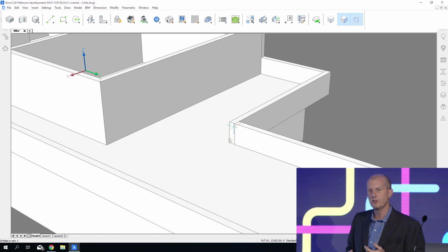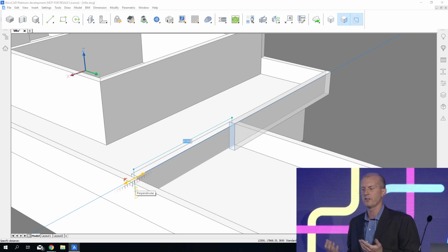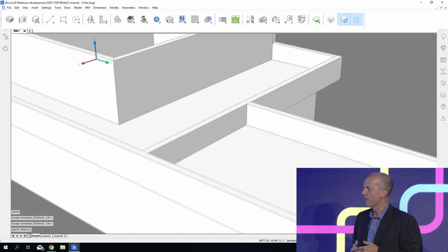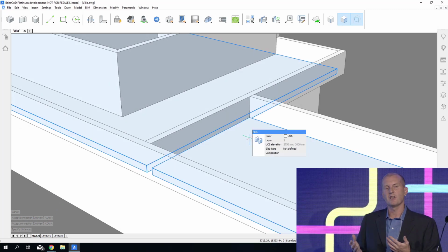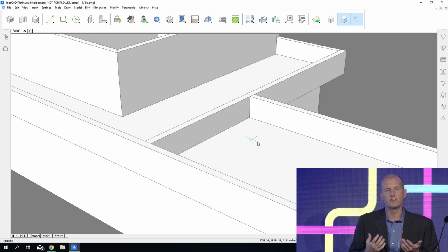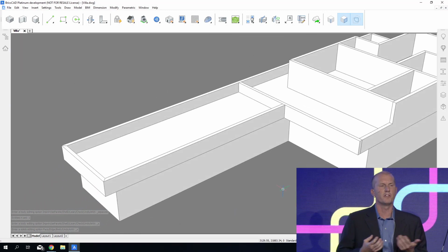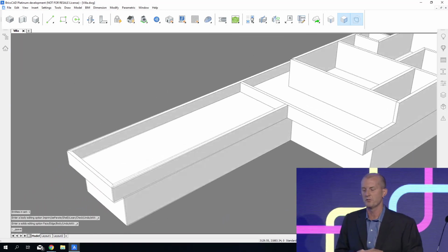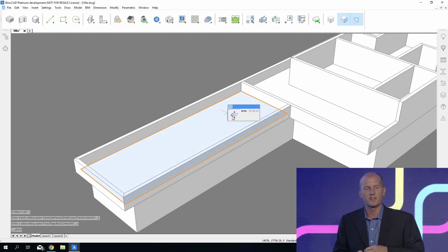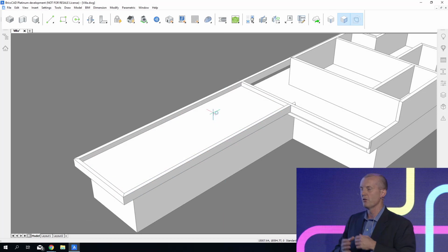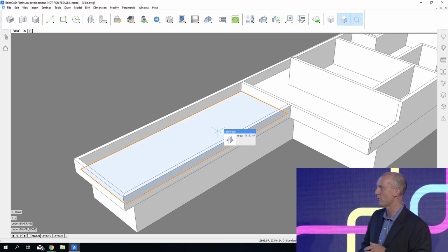There are multiple things that you can do at once when you start modeling with a tool such as this. By extending the wall, what we're actually doing is also splitting the slab into 2 separate members as well. And we can separate those, and then we can start to quickly work with them independently and use tools such as BIM Drag to change the height of them and reposition them for something that we'll do a bit down the road when we start showing how Propagate works.